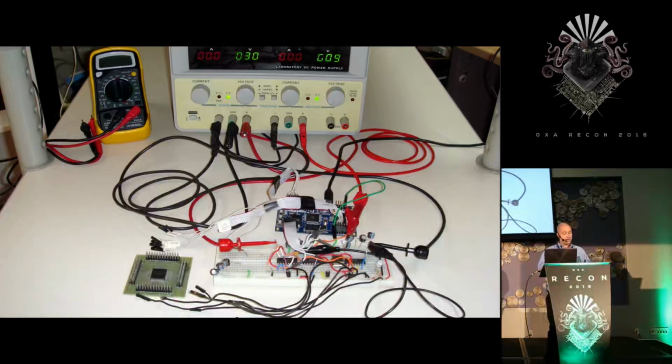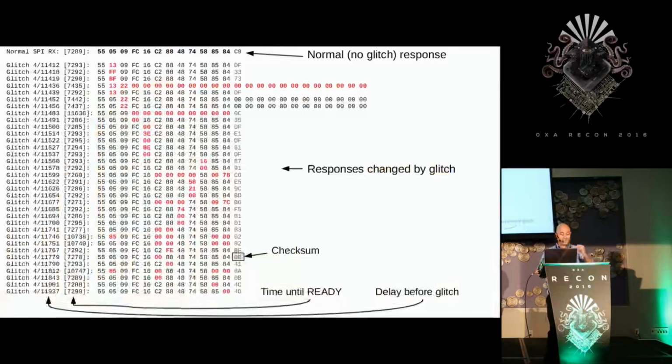So this simple breadboard-based glitcher was very flexible. The breadboard can be modified to test different ideas and can be reconfigured quickly, and I didn't really need to make anything more advanced than this. To test if the glitcher will work, and to find what voltage levels to set it to, we can send a command to the ACP, then glitch, and see if the response is unusual. The general strategy here is to lower the voltage just to the point where the chip sometimes resets due to the glitch. By adjusting voltage levels, glitch length, and timing of when the glitch will land, I succeeded in causing ACP responses to be altered.